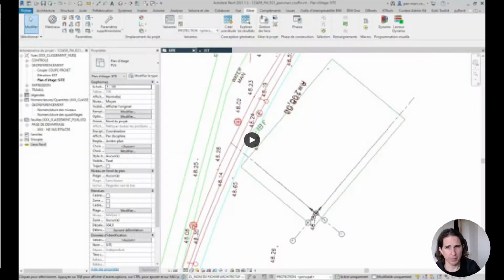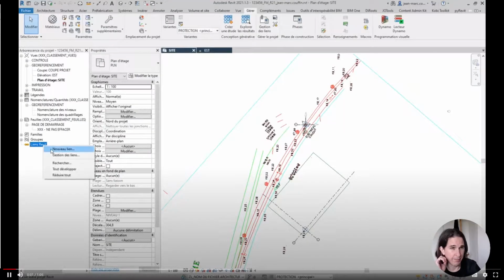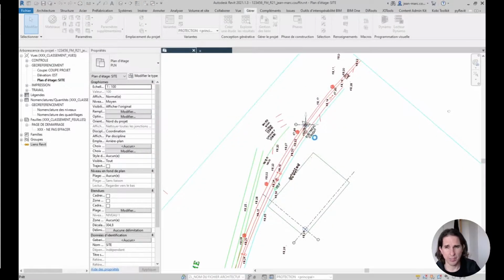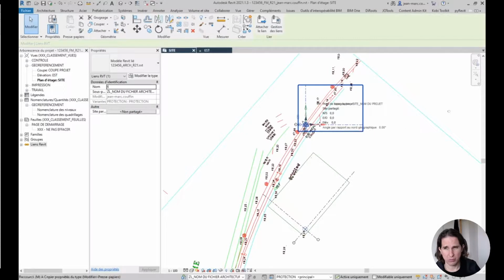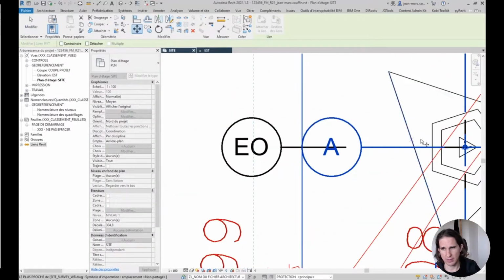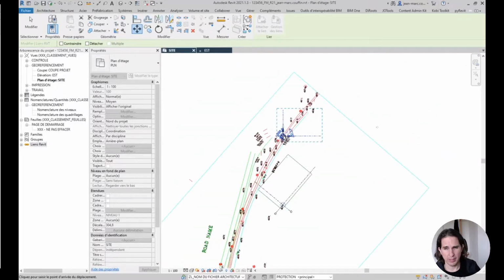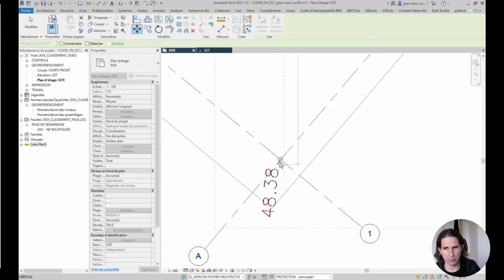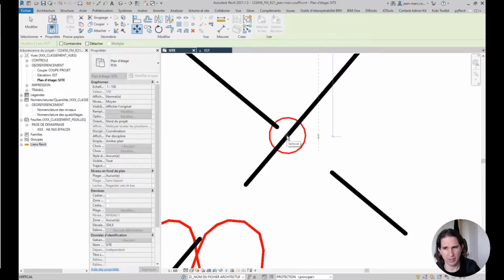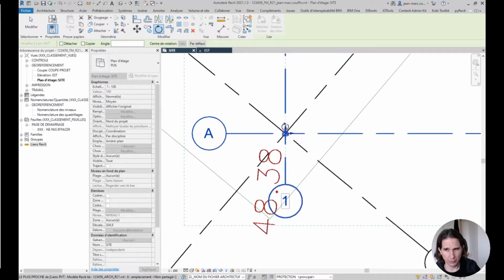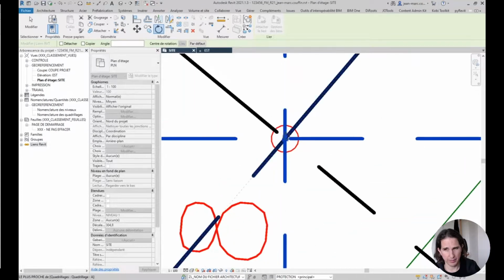And then from there, you need to move them so that you position them properly in all 3 dimensions. That means that once it's inserted, you see it's on the internal origin here, you just move it in plan and then align it with the proper location of your axis set up in your master file. Then you do your rotation if needed to align them.